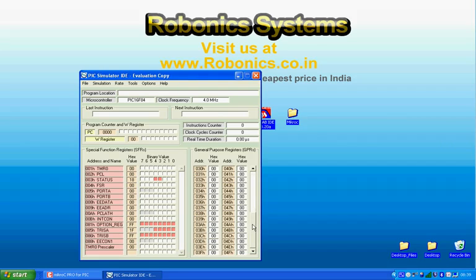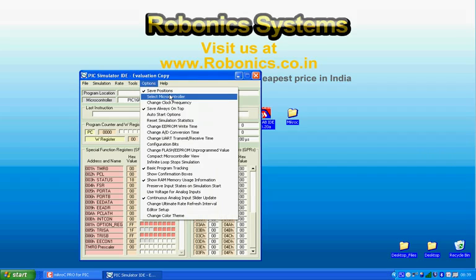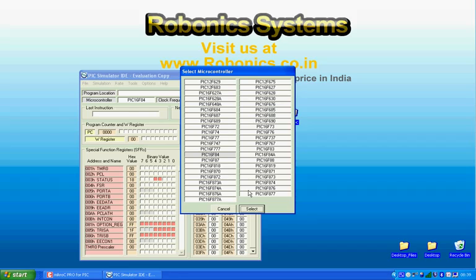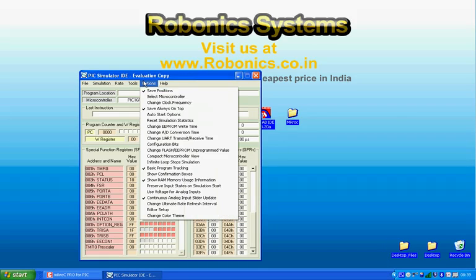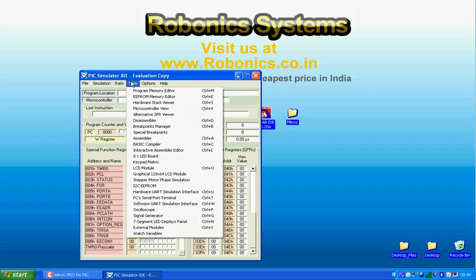First go to Options and select Microcontroller. You will see a list of microcontrollers. This is mostly for the PIC 12F and 16F series, and we are going to use PIC 16F84. Do not worry, PIC 16F84 is almost the same as PIC 16F84A, except that the 84A is the latest version. Click 16F84, click Select, and then go to Options. If you have the compact microcontroller view checked, please uncheck it, and then go to Tools, Microcontroller View. There you go, you see the microcontroller.